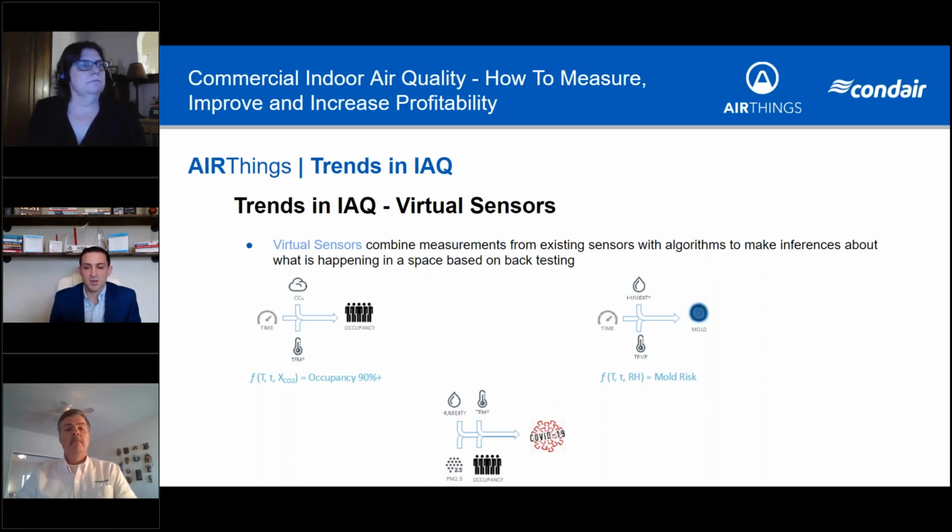And again, we talk about humidification. I think it's so important that we maintain that 40 to 60 RH for our occupant health, but we don't want to do it if we're going to have mold. So again, I think insights like this are critical, where we can really look at all of it, minimizing viral transmission while ensuring we don't have other elevated risks in that space.